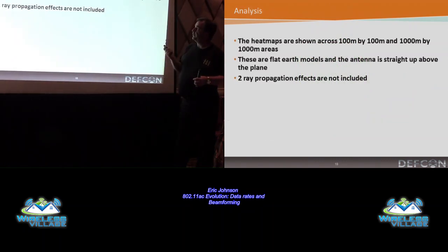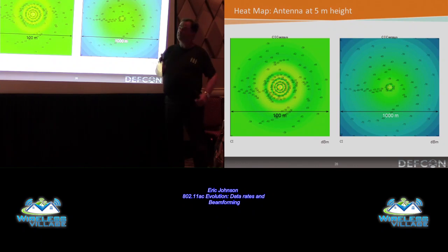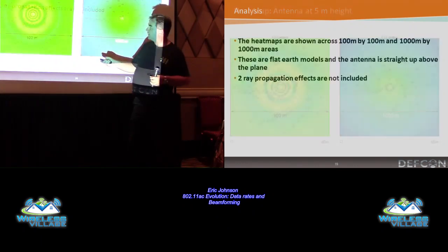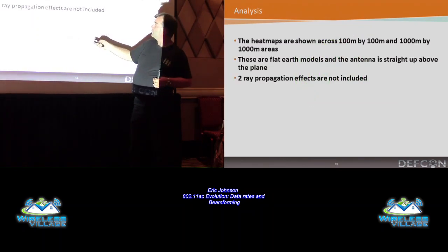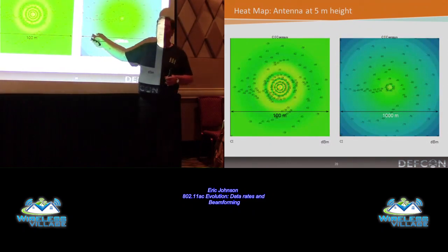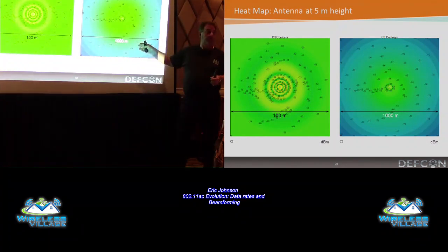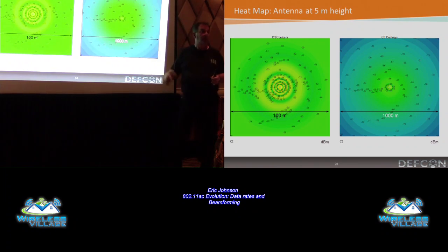Right now, if we take those plots and do this three-dimensionally, this is actually what it looks like when you project this onto a flat Earth model. So the side lobes that you're seeing in here, all these fine ripples, manifest here as the ripples in the power pattern. Okay? This is over a short range. This is 100 meters. And this is over a kilometer. So all of that is compressed down into the center of this picture. Okay, so all of this is just doing trig in the two-dimensional sense, and I'm actually plotting the antenna pattern.